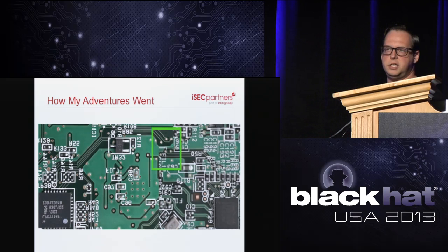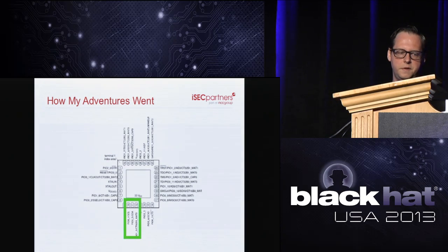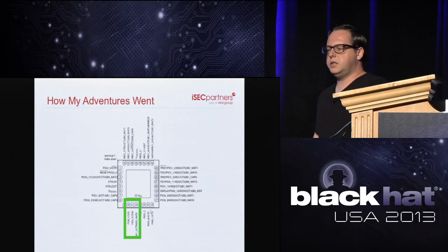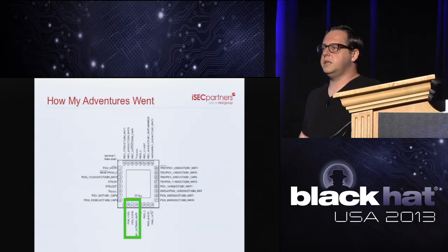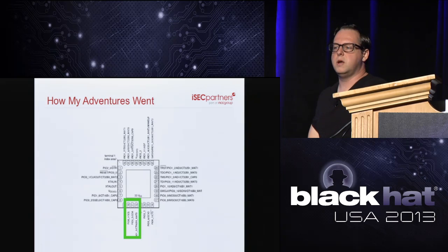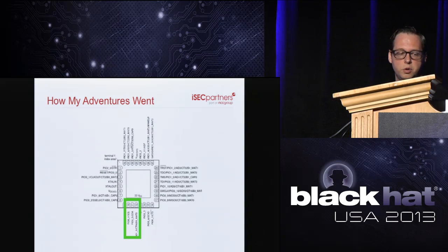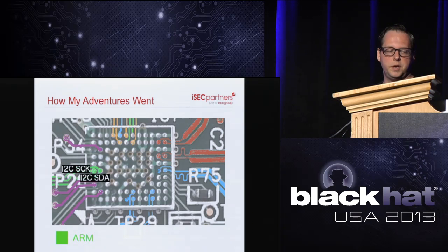So now that we have data sheets for our ARM, let's go ahead and figure out what these are. Looks like 2 of them are I2C. For those who are not familiar, I2C is a bus for two chips communicating with each other. So it looks like the ARM and the Thunderbolt controller are communicating via I2C. We can add those 2 pins to our pinout for Thunderbolt.